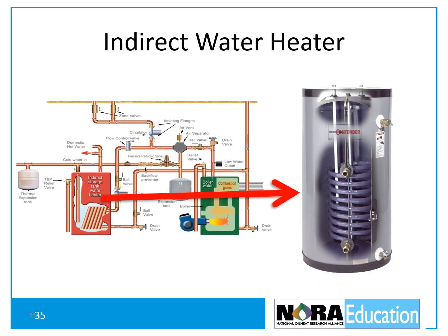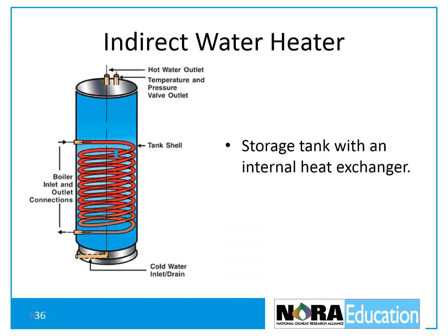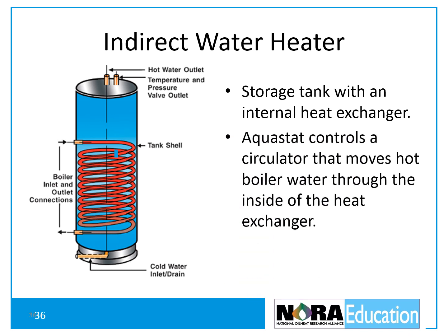Indirect water heaters. Indirect water heaters are storage tanks with internal heat exchangers. They are equipped with an aquastat that controls a circulator to move hot boiler water through the inside of the heat exchanger, heating the domestic hot water in the tank.